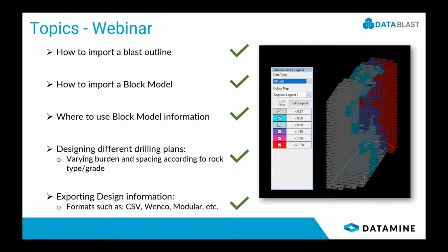Okay, so all in all, in a few words, the block model functionality does not replace the grade control system, as I have said before, but it's really useful if you have only a resource model. It can be really helpful for the operational team to plan and design the drilling patterns. The usage of predefined blast block outlines is really helpful as well, because you can trim the block model according to the blast block you're working with.